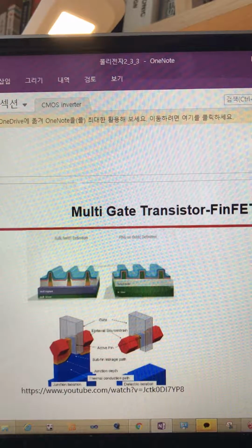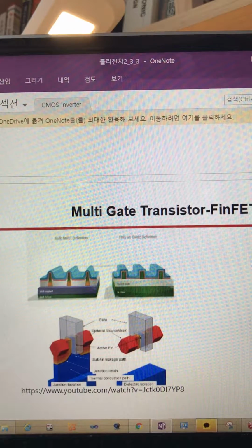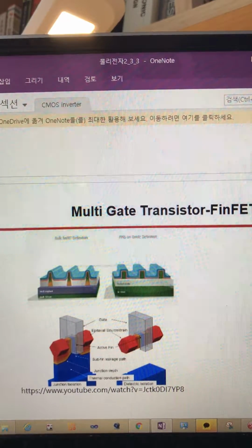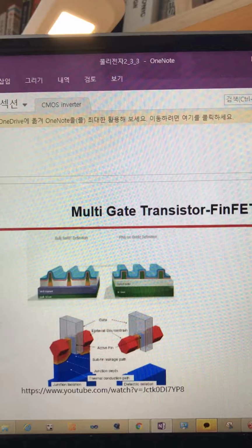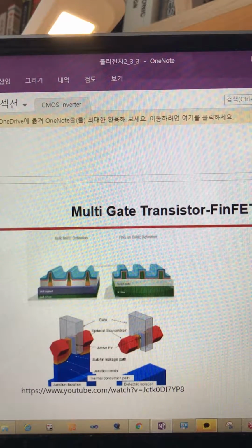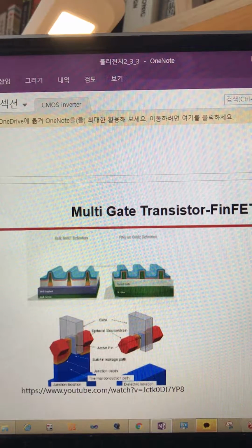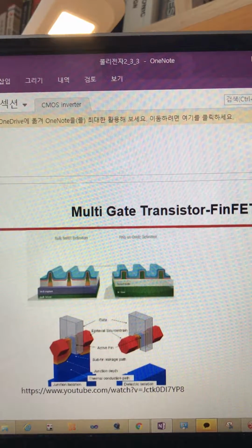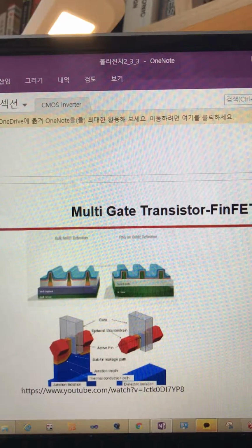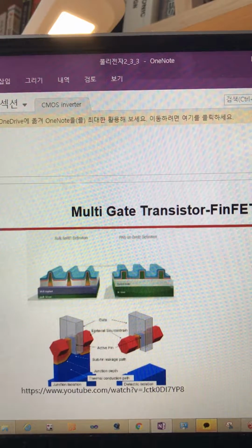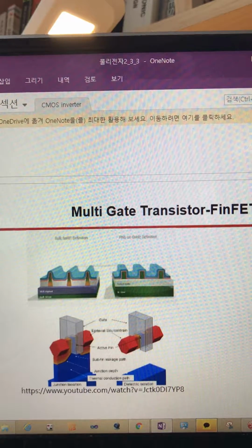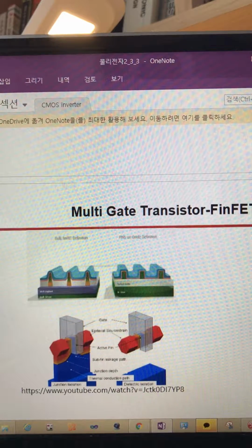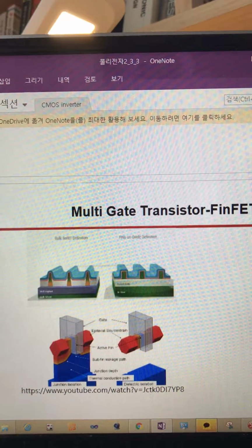So, when this goes to FinFET, the thinner the body, the more current flows through the channel. The thicker the body, the harder the control in the body becomes, and the worse the punch-through or roll-off. Also, the resistance of the channel increases and the transistor becomes larger, eventually resulting in the series resistance phenomenon.